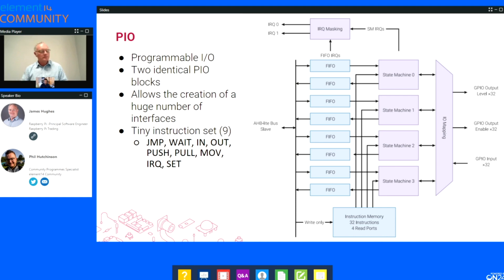What's it there for? Well, interfacing with other digital hardware is hard. It happens at very high frequencies due to the amount of data that needs to be transferred, and has very, very exact timing requirements. And PIO is our response to the problems of bit-banged interfaces, really. You can do that sort of thing by just programmatically pinging GPIOs up and down. But then, you're right, the code is very complex and at the whim of something else happening in the system.